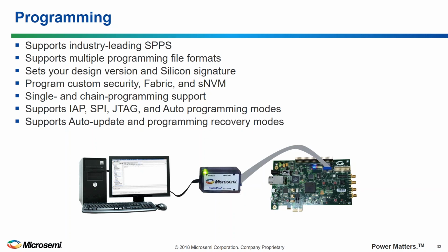So that does prevent overbuilding, but you don't get the report back, you know, to verification of things like you can with the SPPS. SPPS works for SmartFusion 2, Igloo 2, and in PolarFire because we have additional security features. So with those devices, both those families, you can drop ship a blank device and you can have everything programmed in, whereas with the CPLD replacements, you would have to have the key programmed in a trusted environment because somebody's going to know what the key is. Once you've done that, you can create an encrypted bit stream and give these devices. So there is a way to prevent overbuilding. It's not as elegant as it is for SmartFusion 2 or PolarFire.